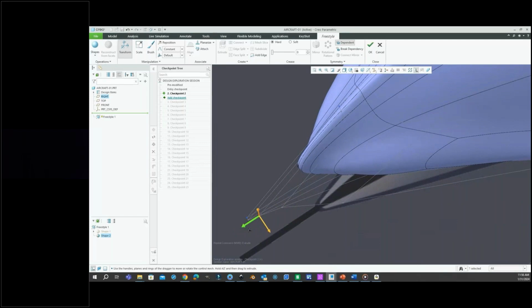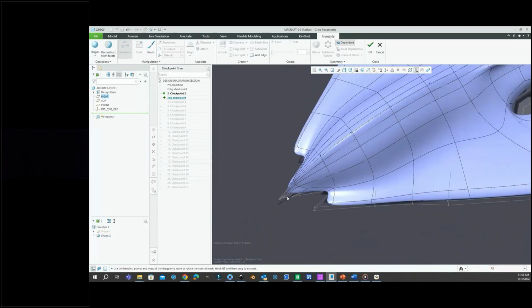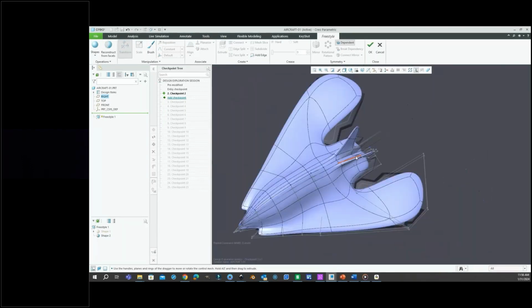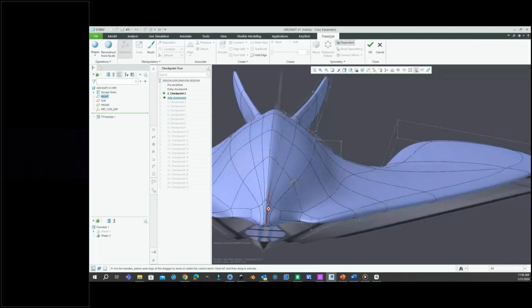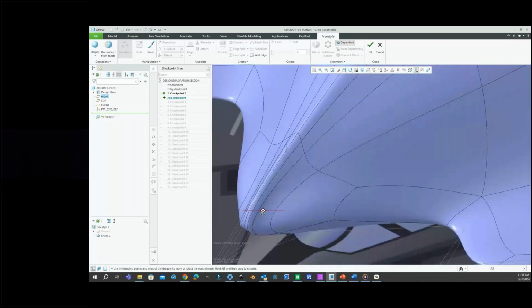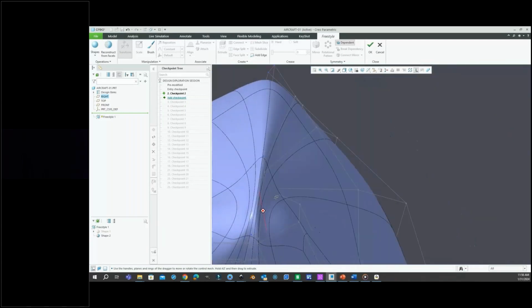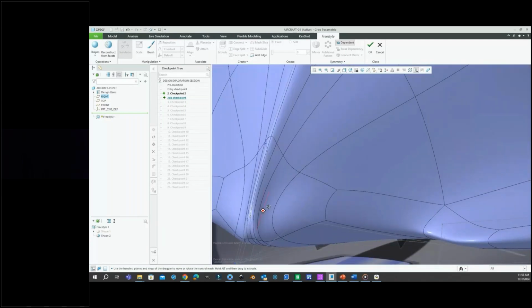And also, we don't have to have geometry in all places. So even though I split the mesh here and that line control went all the way down, I could have limited where that line ended so that I didn't get more geometry on the nose, because I may not need all this geometry to define the nose.